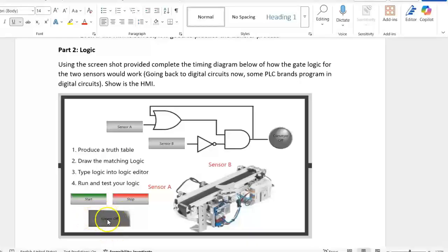This is an output. So if you push the start button, you want to put in a start-stop circuit, and the output would be system variable. And when you start it and you have holding contacts across your start button, this light will come on. This will enable the machine. So let's look at the logic.